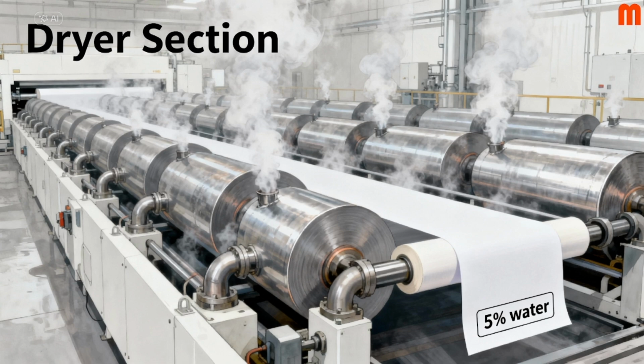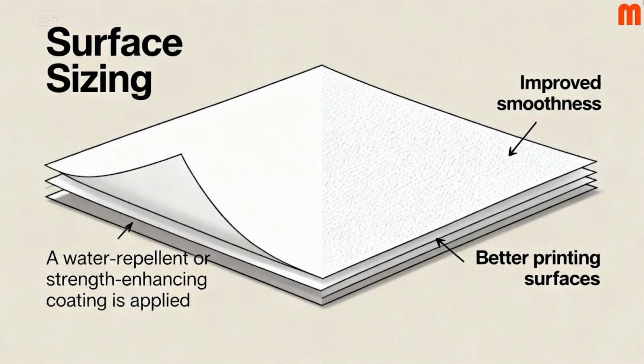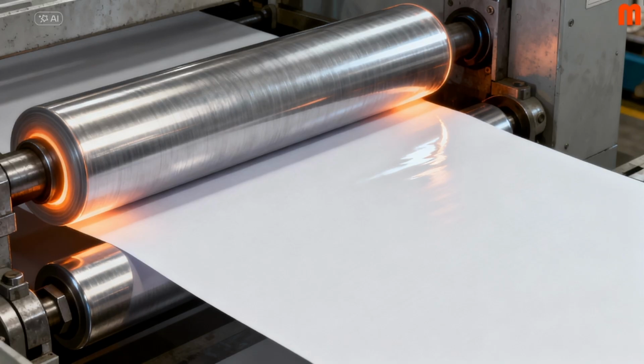4. The dryer section. Dozens of giant steam-heated cylinders evaporate the remaining moisture. By the end, the sheet contains only about 5% water. 5. Surface sizing. A water repellent or strength-enhancing coating is applied. This improves smoothness and creates better printing surfaces. 6. Calendering. The paper passes between heated steel rollers, enhancing gloss and uniformity. This gives paper its final finish.